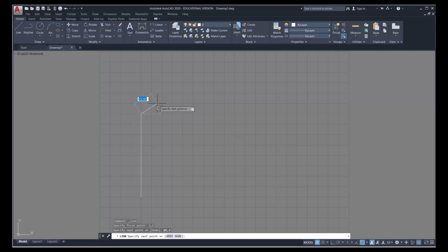And what this does is simply identify we're going 0 along x, 4 along y. Now let's move to the right 2 units. Well, in order to do that, we're moving along x and not y, so we'll type in 2, 0. You can see that the x and y position, or the order that we're typing the information in, is very important. And we must get used to the fact that x comes first and x is horizontal.